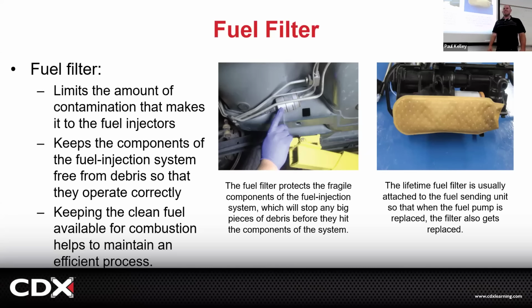Oh yeah. And so sometimes what you need to do is learn to work like this. Like you got to make a drip location so it'll drip off your elbow, right? So this wasn't like amazing work. Like we all did it, but it was never like, oh yay, I get to do a fuel filter. We were doing these fuel filters every 30,000 or sometimes less miles. So like a 30K service would be air filter, cabin air filter, oil change, spark plug wires, cap, rotor, fuel filter, like a pretty big major maintenance.